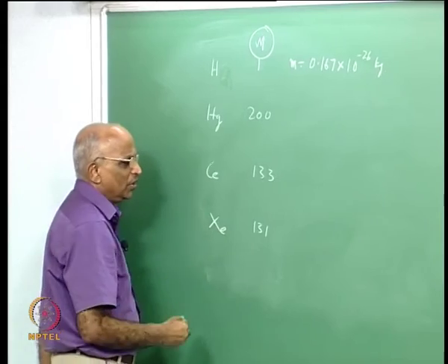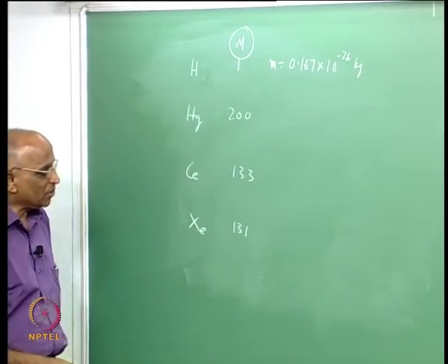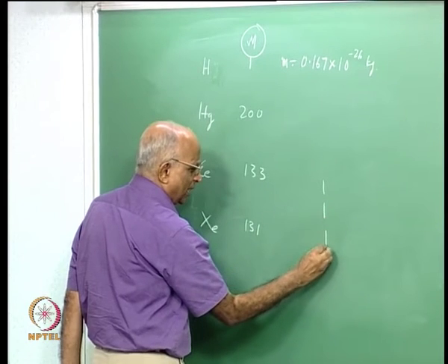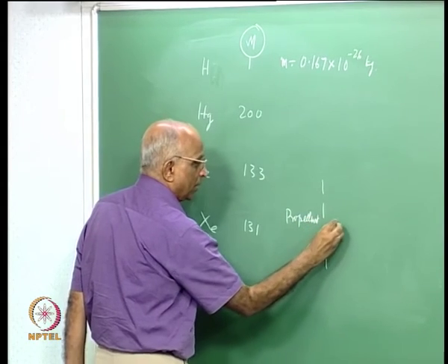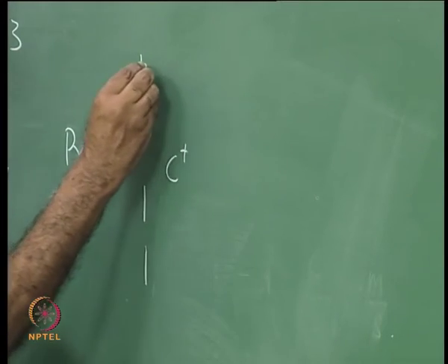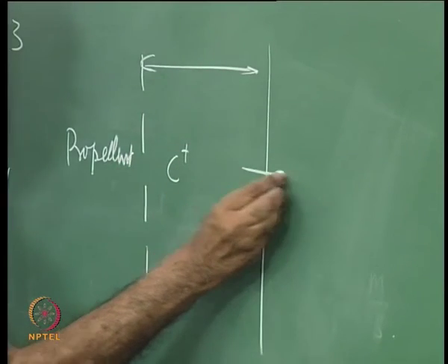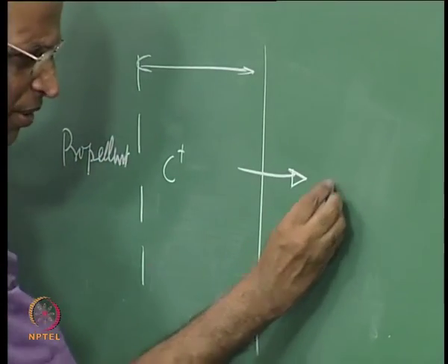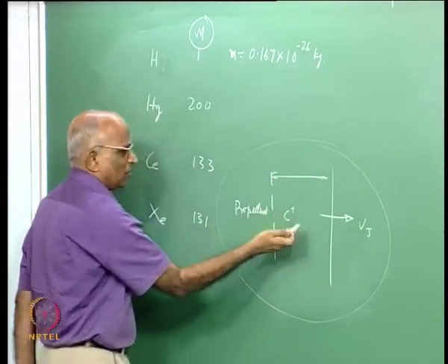We have still not described what the propulsion system will comprise of, but more or less I have to first take a substance like a propellant, convert the propellant into gas or make it charged in some way, then put a field over here, that means a potential difference which will give it a velocity, and maybe put such a potential difference such that I get a high jet velocity, and this is what gives me something like an electrostatic propulsion.